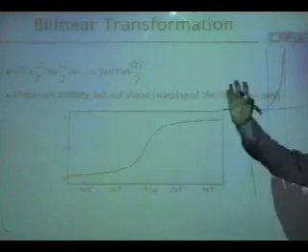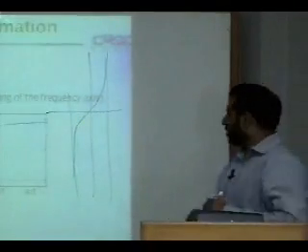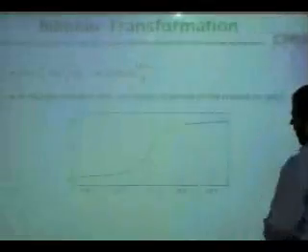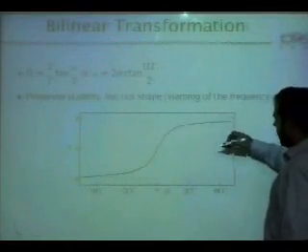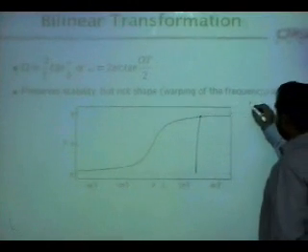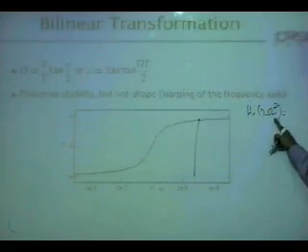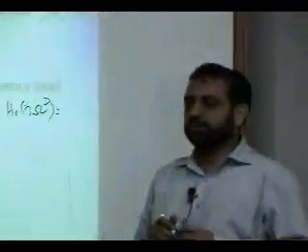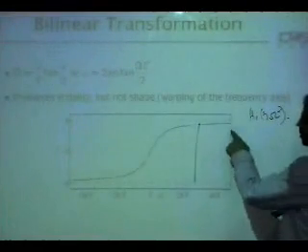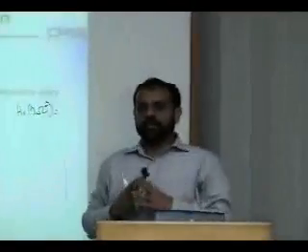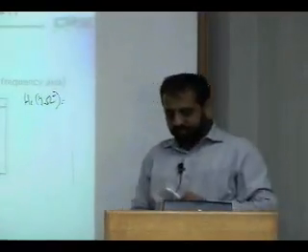It never goes beyond these two lines. So this will make sure that for every value of omega, this is how you translate. You say, okay, for this value of omega, HC of j omega, you pick an omega and draw it on the small omega axis. This value becomes this value becomes this. If you do that, no matter where you go, you never cross pi and minus pi. So your discrete spectrum is guaranteed to fit into minus pi and pi.